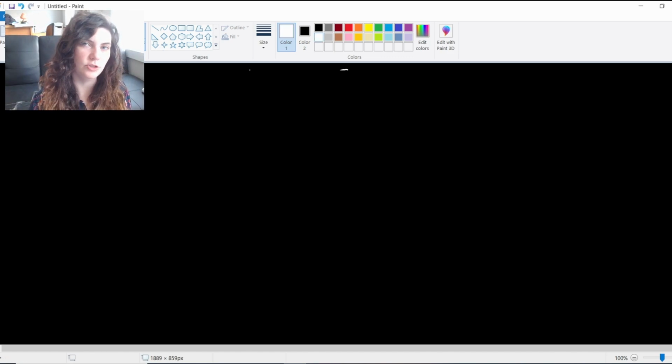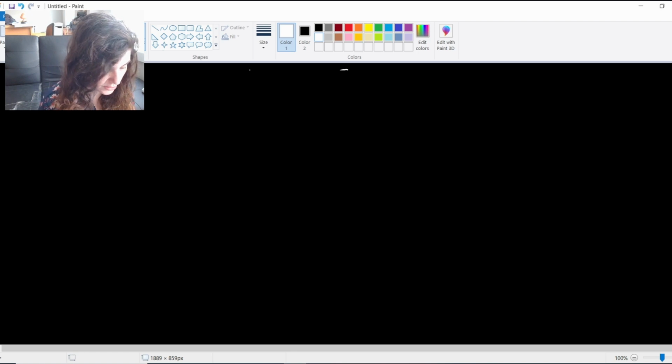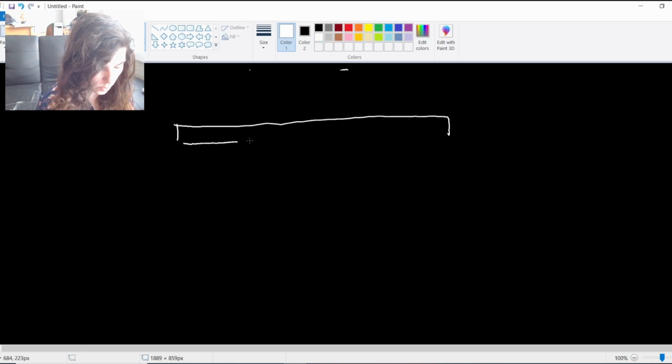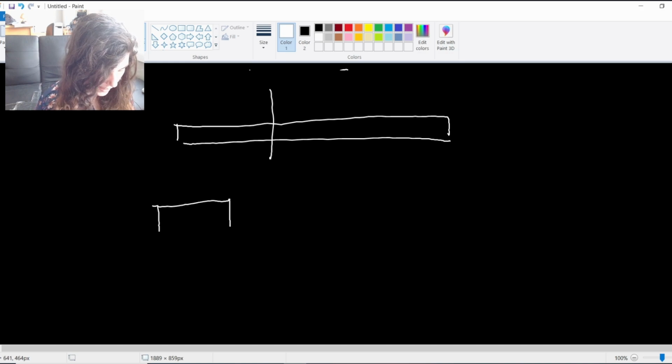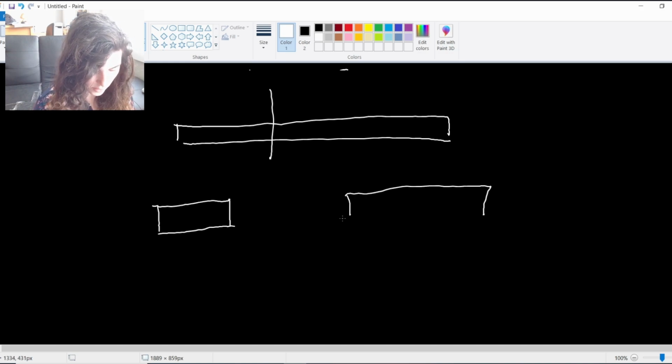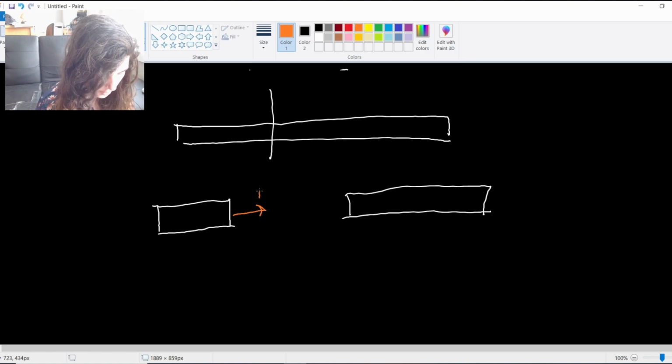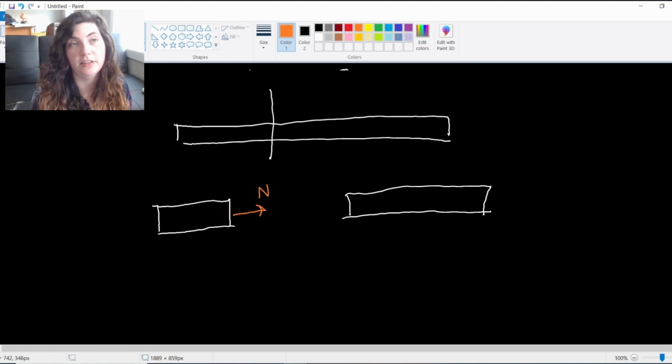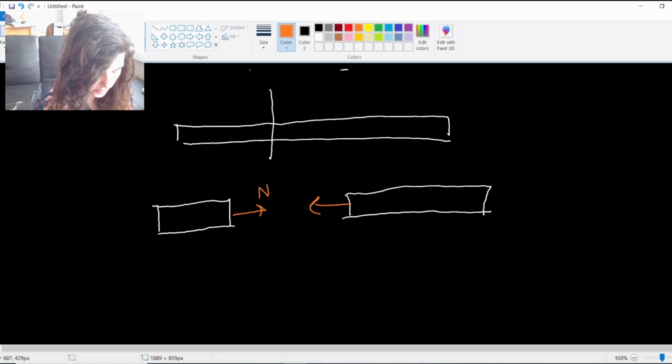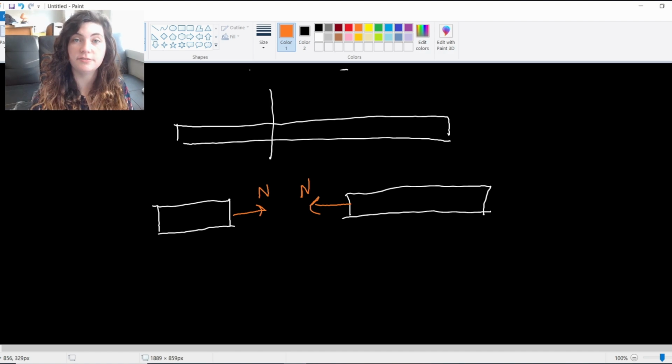Another thing to note about these internal forces is that they are equal and opposite, right? These internal forces, if you split the beam at one location, say right here, when I have two halves of my beam, it works a lot like how we saw in frames and machines, where if our normal force is going positive in the x direction on the left-hand side of the beam, it is now going to be pointing to the left on the right side of the beam.